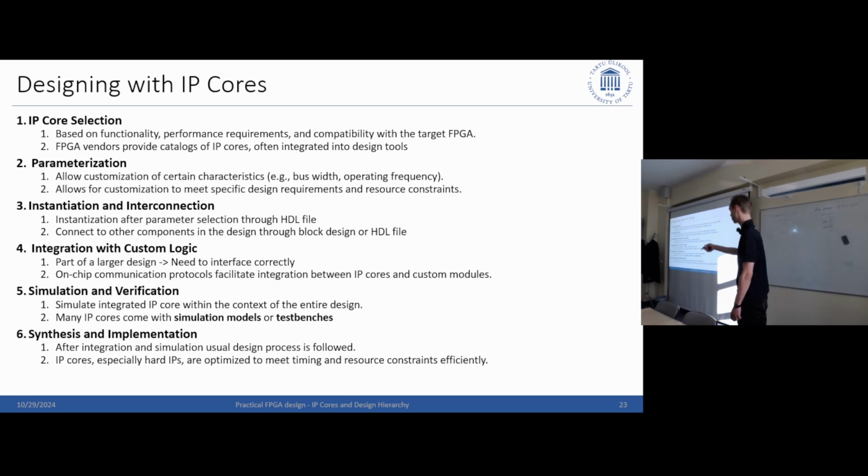And then you just follow the rest of the workflow. You simulate your design, you check that it works as it's supposed to. Honestly, if you have something like Vitis AI, you might not even simulate it, because this IP core is so huge and complex that it would take very long to simulate. But if you have a smaller IP core like a FIFO, you want to see that you correctly load the data in and out. And then synthesis and implementation, just the rest of the workflow. Basically you can do optimizations here, different routing algorithms, and those kinds of things.